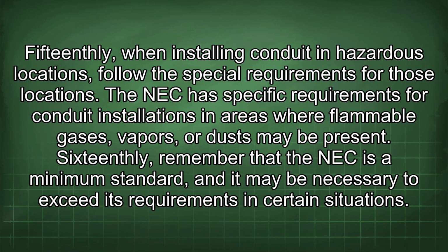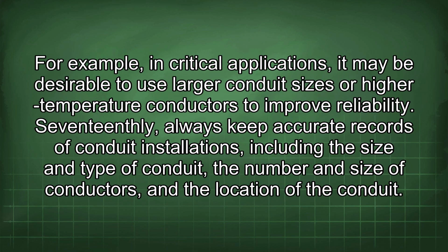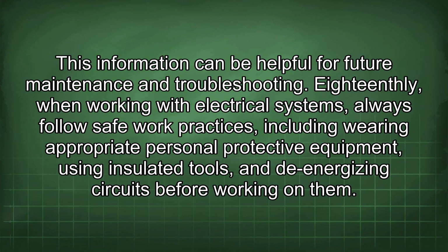16thly, remember that the NEC is a minimum standard, and it may be necessary to exceed its requirements in certain situations. For example, in critical applications, it may be desirable to use larger conduit sizes or higher temperature conductors to improve reliability. 17thly, always keep accurate records of conduit installations, including the size and type of conduit, the number and size of conductors, and the location of the conduit. This information can be helpful for future maintenance and troubleshooting.